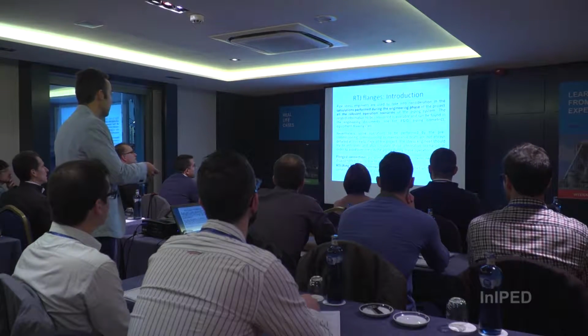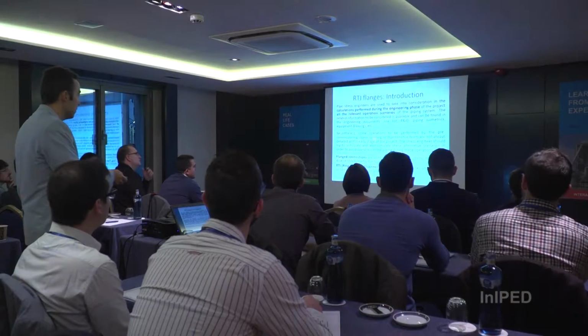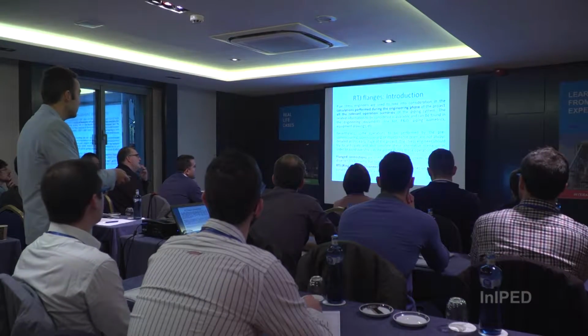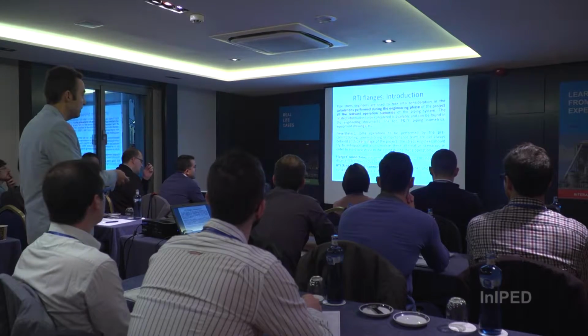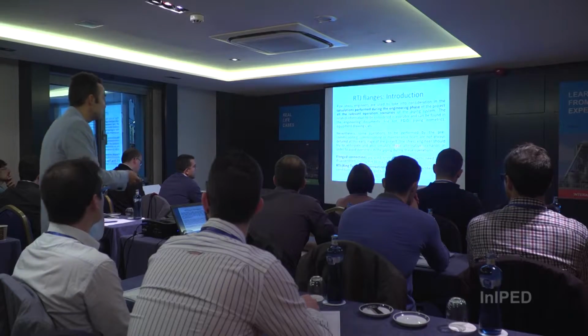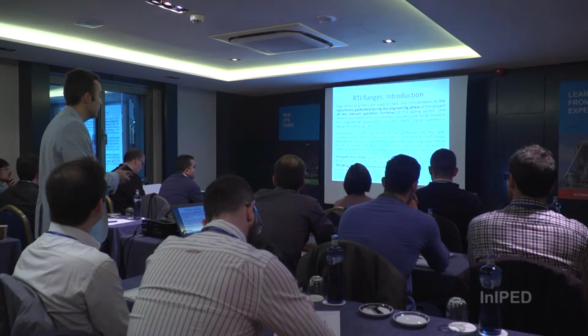But what happens with the operations to be performed by pre-commissioning, commissioning, or maintenance activities? This information is not so clear or always available at this early stage of the project. Then the stress analyst has to solve this problem. Try to anticipate and simulate these alternative scenarios. It's very important, the collaboration with the pre-commissioning or the commissioning specialists.